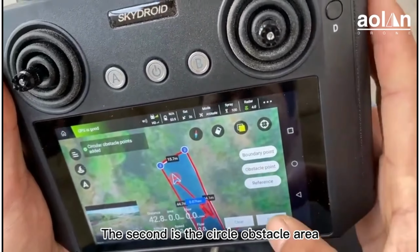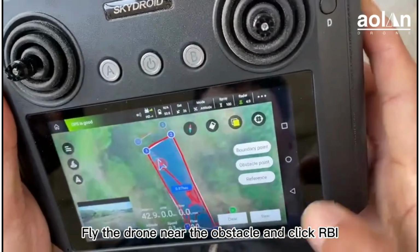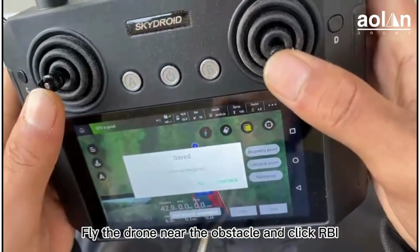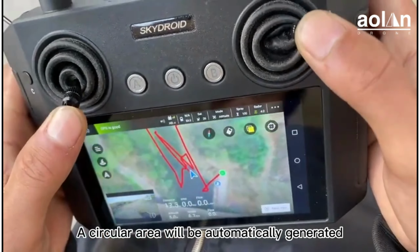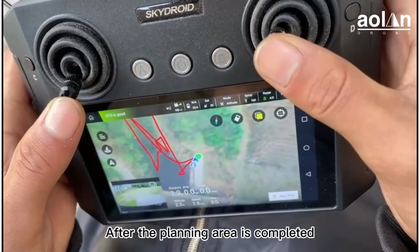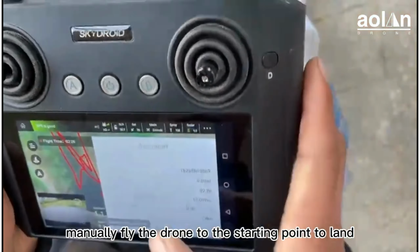The second is the circle obstacle area. Fly the drone near the obstacle and click RTK. A circular area will be automatically generated. After the planning area is completed, manually fly the drone to the starting point to land.